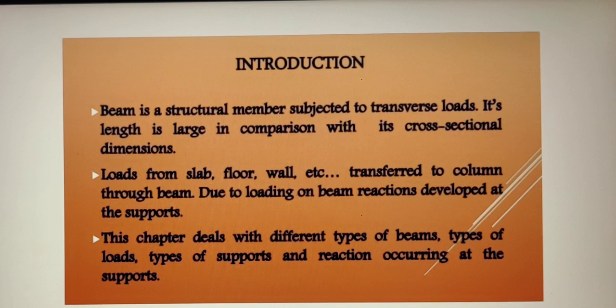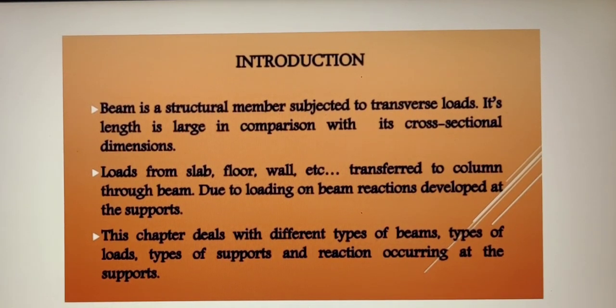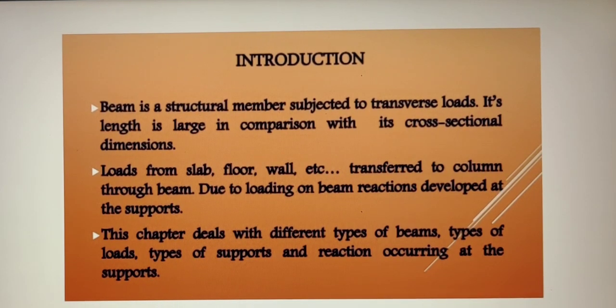Now the purpose of the beam: load from the slab, floor, wall, etc. is transferred to the column through the beam, and through the column it is transferred to the foundation. Due to the load acting on the beam, reactions are developed at the supports. In this chapter we are mainly dealing with the different types of beam, different types of load, different types of support, and the reactions occurring at the support.